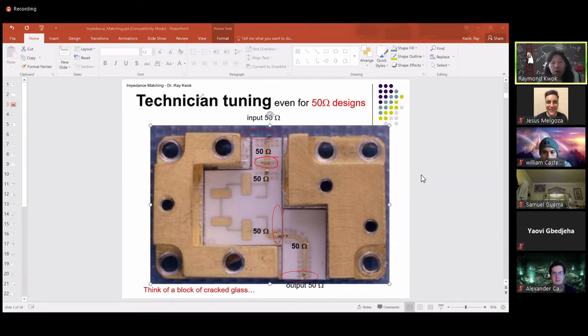Right. So when the technicians, I'm going to take this out also. And this piece here. Around the corner. Do you see that? See a little bit of, okay. That's what they do. That's how they make it work. That's how they tune it and make it back to 50 ohms or close to 50 ohms, right? By putting a piece of ribbon somewhere along the transmission line.